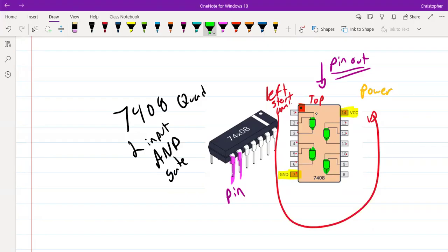On these items, remember it was important that we know what the directions are of what stuff comes in and what stuff comes out. This 13 and 12, these are our inputs. As you see, they go through and into the AND gate. We already have talked about gates. Remember we said that one side is the input, and then the other side, like on pin number 11 coming out, this will be the output of that gate.